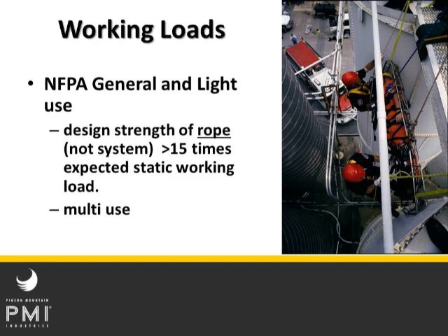So you need to know what your use is, and whether you want a general use or a light use. A lot of teams are using light use ropes all the time with multiple people on them, and they don't have any problems. It's because they are enough of a technician to be able to figure out their loads and their safety factors, and even with a lighter use rope, they've got their 10 to 1 or whatever they felt was their safety ratio that they wanted to have, and they were able to rig that up using a light use rope. There's no reason not to do that, but that's a departmental decision that I can't make for you.